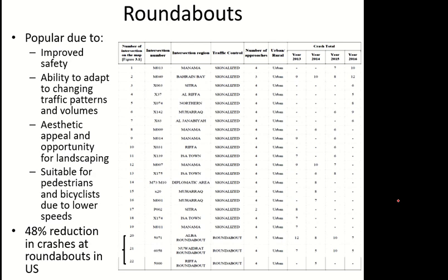Okay, and this can happen during the day as well. So you gave one side priority on a signal. And now this side in the evening has very low traffic, so you gave this side more timing in the morning. But you cannot continue with the same timing in the other hours because this side will have less volume. So I need to go and program the signal for different timings. But on a roundabout, you don't have to do this.